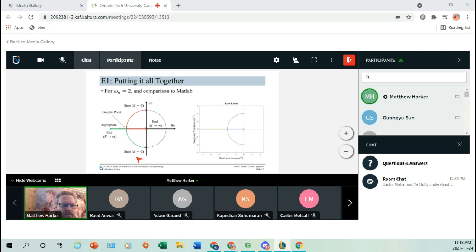We put it all together and we ended up with a root locus. So we had these two branches. We basically have two poles. One goes along the circle here and then off to infinity. The other branch comes around the circle the other way and then heads to that 0, right? So that's in sum the locus of our damping curve.